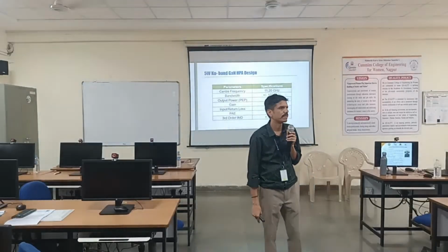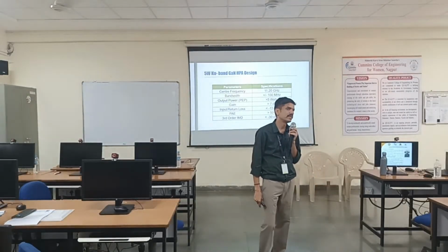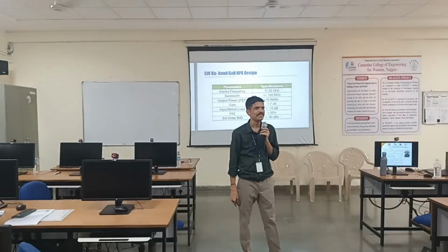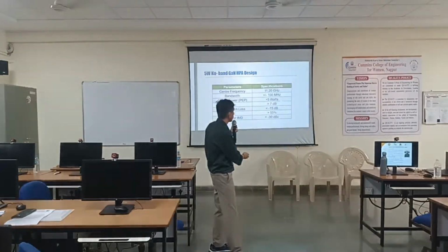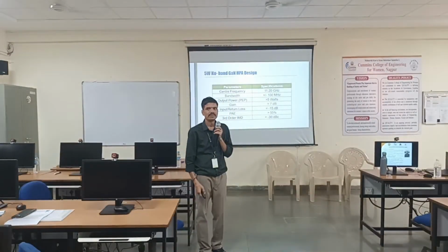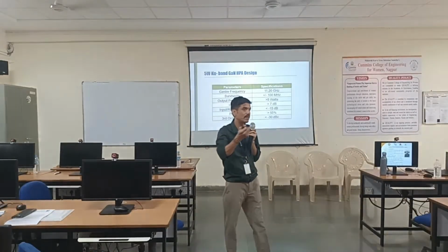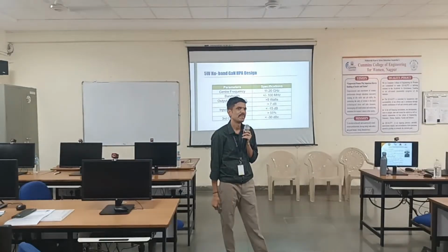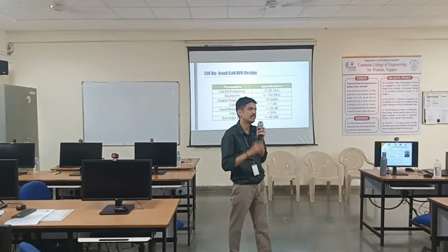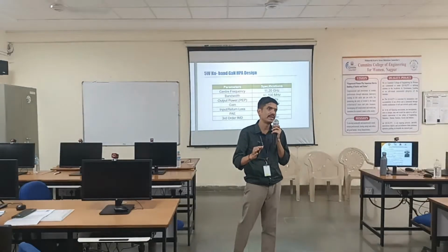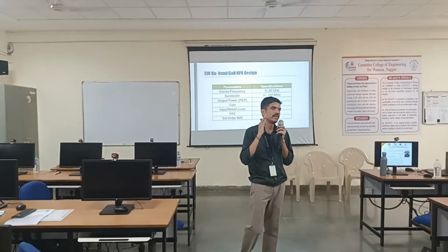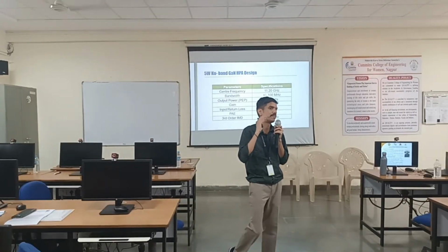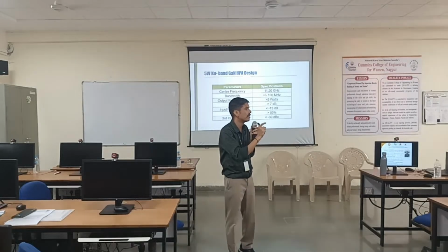Because we have not considered the operational compression region. This 7 dB gain is compressed gain. So some professor was asking me about the GAN and silicon. Now he is not here, so I would have continued that discussion. All these GAN PAs will always operate into 3 to 4 dB gain compression.